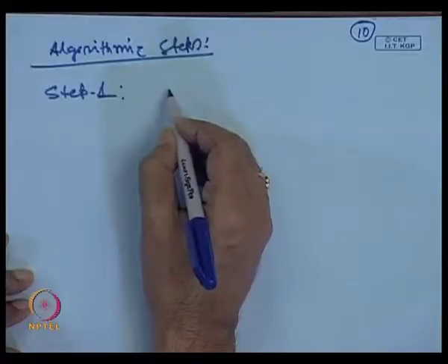Agree? And the remaining n eigenvectors of this Hamiltonian matrix are such that the eigenvector has dimension 2n cross 1. The first n rows are denoted by V 1 and the remaining n rows, that means the last n rows, are denoted by U 1. So, from that information we can find the solution of P, and in this method the Schur method gives the computation of the eigenvectors of H m corresponding to the stable eigenvalues mu 1, mu 2, up to mu n. So, first step is to form